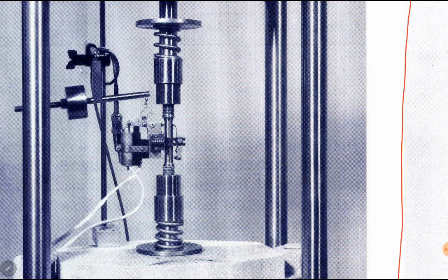Okay. First we have to find forces in each member. Here is a free body diagram of BDE, which is a rigid member. At point B there is force AB, and point D there is force CD. Initially we have indicated both the forces as tensile forces acting away from the body. This 30 kilonewton force is given.